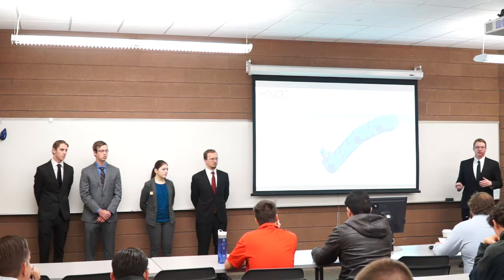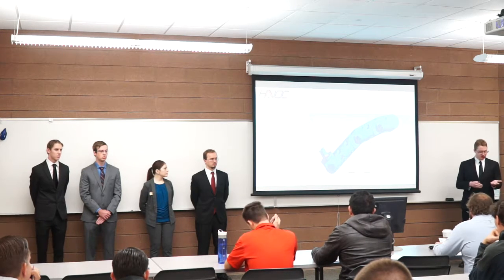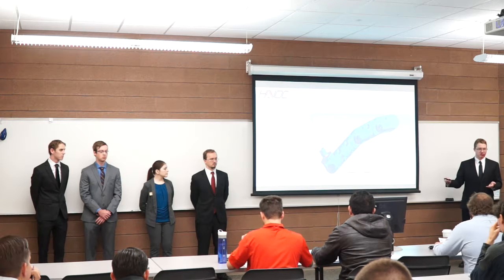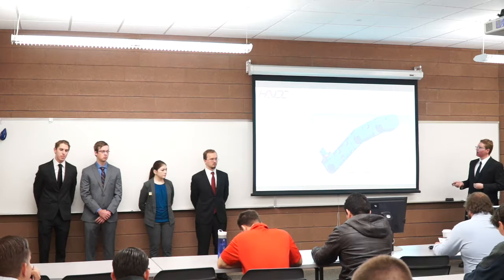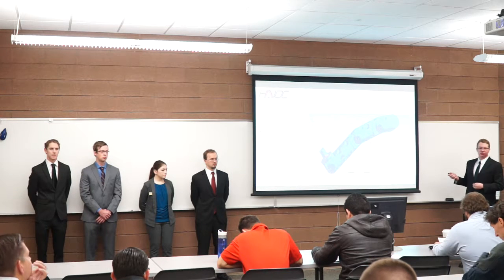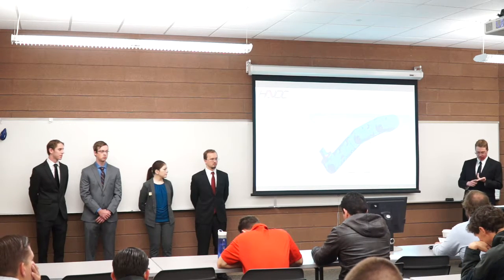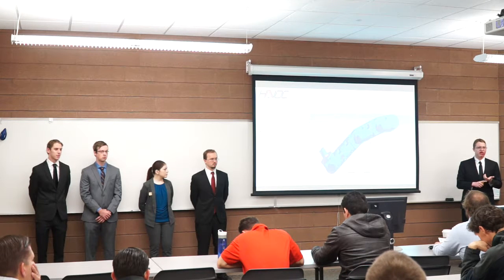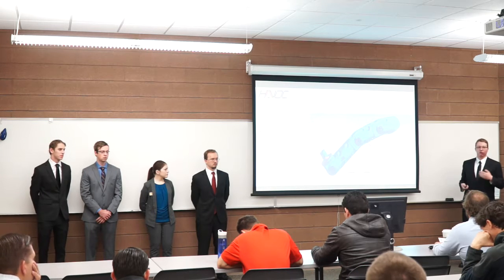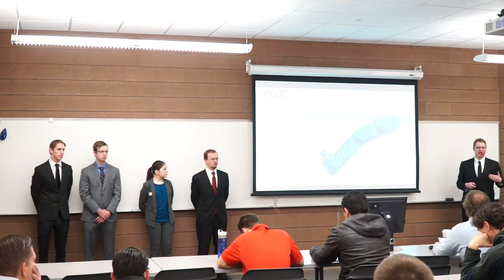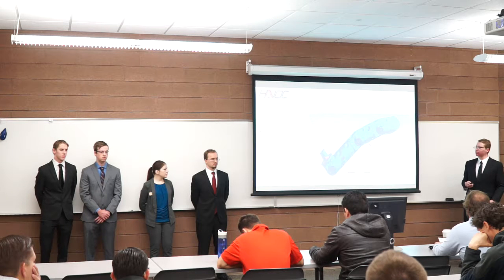The fingers were tested 5 pounds each to distribute the factor of safety 20-pound load across each of the individual 4 fingers. And that was applied to the center of the finger. And that showed that the maximum tensile strength and strain were not exceeded by that force application.